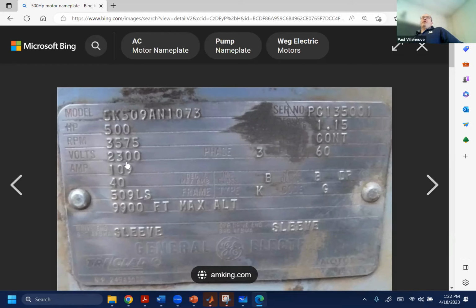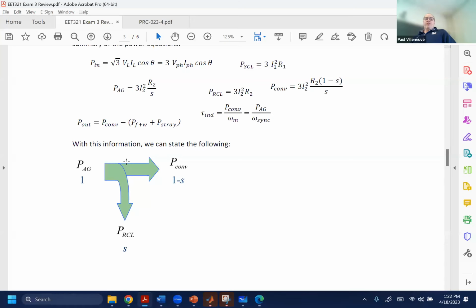Most people won't even go in their circuit breaker panel, which is only 120, 240. But once you start pushing medium voltage, you get higher arc flash energy. We've talked about that in this class, but arc flash is how you die if you're an electrician. Most of the deaths from electrical issues aren't from shocks, they're from fire, because you get an arc and that has a lot of energy.